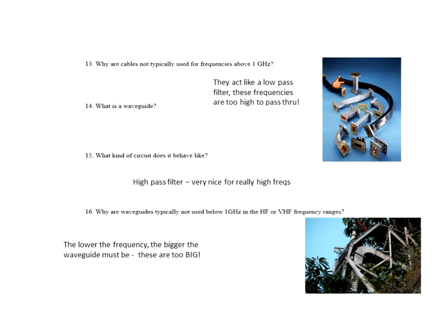Waveguides are just metal tubes that you shoot your wave into one side from the transmitter. It's received at the other side by the receiver. You're guiding a radio wave through a waveguide. We typically use waveguides for very, very high frequencies, UHF, SHF, and frequencies above. Waveguides are very, very popular for satellite and high-power cell phone communication. And the reason is you want to stay away from coaxial cables and twisted pair, especially at those frequencies.